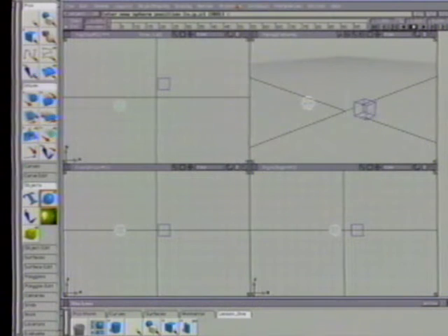Change the current frame to frame 1. Go to the Animation menu and choose Set Keyframe. A keyframe is set for frame 1. This is a major change for version 6 users. In the past, the default method of setting keyframes was based on a system prompt instead of the current frame. While the old method is still available, the current frame is the new default used to set keyframes.